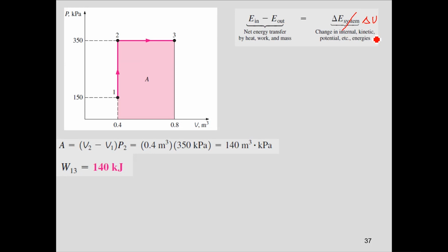And in terms of energy in and energy out, you have to find out the energies which are coming into the system and the energies which are moving out of the system. So essentially, you have Q in, which is being supplied to the system, and boundary work, which is due to the expansion of your system. It is equivalent to delta U, or to mass multiplied by the specific enthalpies of air at 300 Kelvin and 1400 Kelvin. So Q in is something you need to find out. Boundary work you have already determined to be 140 kilojoules.